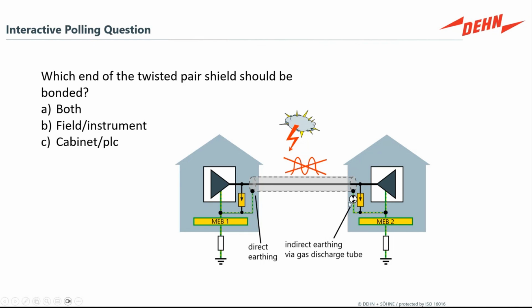And in this case, what we're showing is that you still apply surge protection, and you apply surge protection on that shield. You indirectly ground the shield with a gas discharge tube. And this acts very much like the thermal sensor on a water heater: if there's enough voltage built up, if there's enough pressure on that shield, that spark gap will discharge and equalize the pressure, equalize the voltage on that shield. And otherwise, it stays open, and it does not create a loop or a noisy environment.